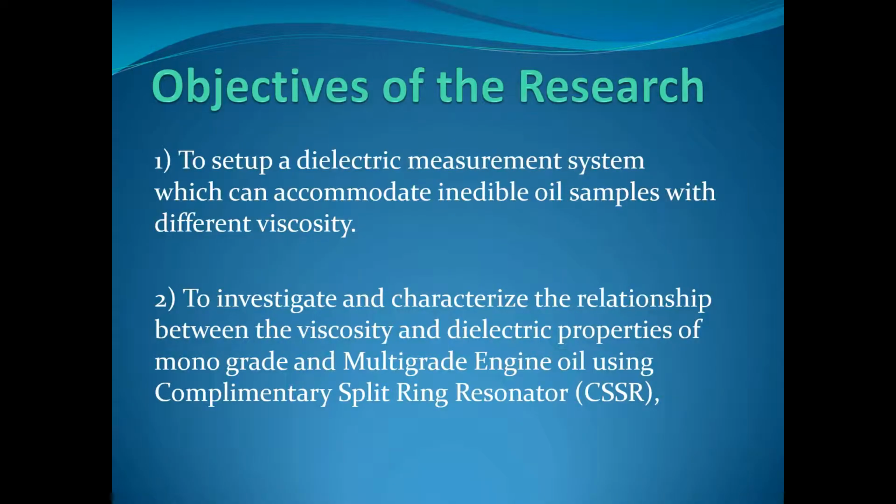Let's go to the objectives of this research. First, to set up dielectric measurement system which can accommodate inedible oil samples with different viscosity, this engine oil. Number two, to investigate and to characterize the relationship between viscosity and dielectric properties of monograde and multigrade engine oil using complementary split ring resonator (CSRR).